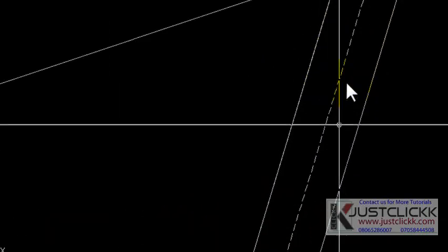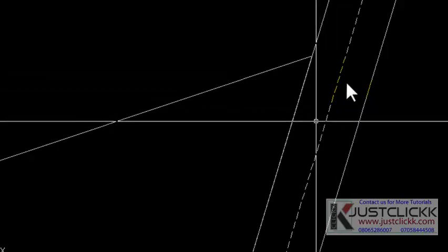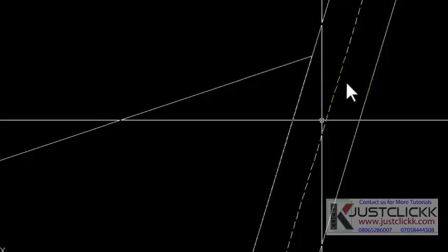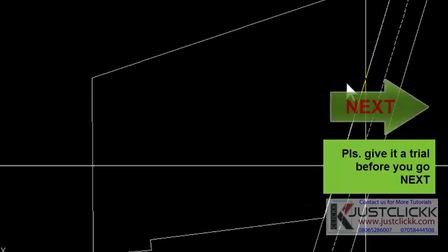So 100. Have it in mind that during printing you have to be updating the site plan, the dotted line. When it comes to site plan, you have to make it 100. When it goes to the main drawings, you have to change it to 25, which will give you precisely the scale for each drawing type. So that is how you create the access road.